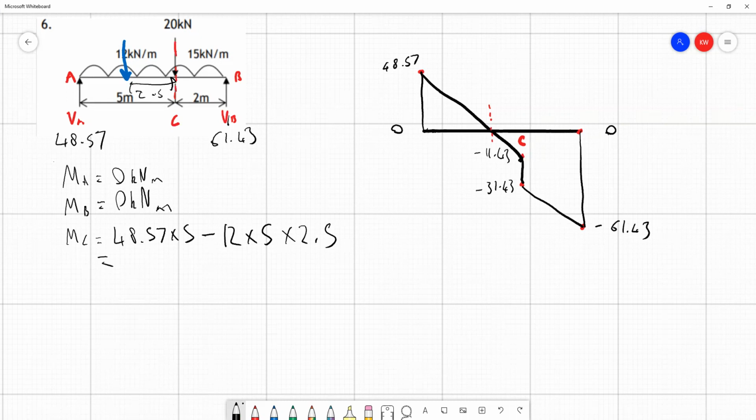And that works out. So I've got my calculations right, and I think I have 92.85 kilonewtons. So I'll quickly draw in what we've got so far in our bending moment diagram. A wee bit of room over here. So that's our 0 line. MA and MB, which, if you question why they're 0 again, look at the other examples, but if you're just not sure, do ask me.